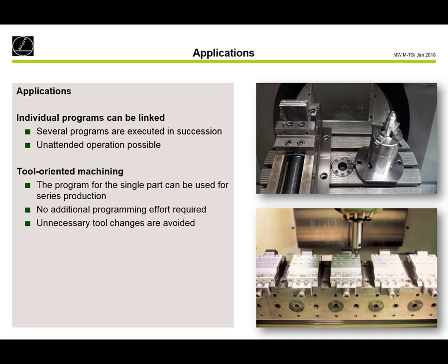I can also do tool-orientated machining. So if I have a multi-clamping system with a lot of the same workpieces on it, then I can use the tool-orientated machining to save tool changes.